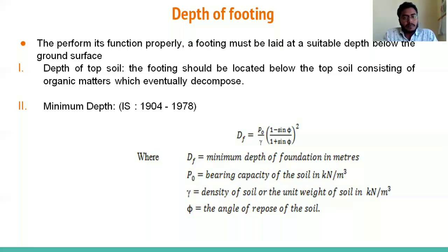So whatever the minimum depth you get by this formula, we will provide some extra depth. Suppose by using this formula we get the depth of foundation as 1.5 meter. So we will keep 2 meter, right? We will go to the safer side, right?